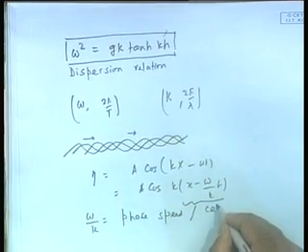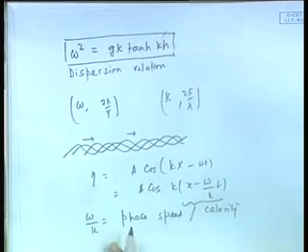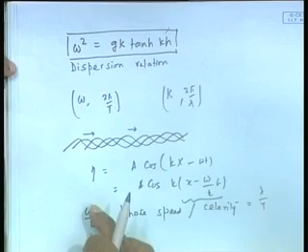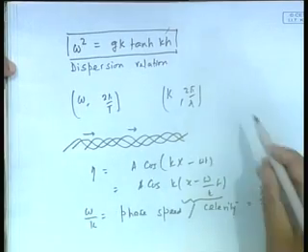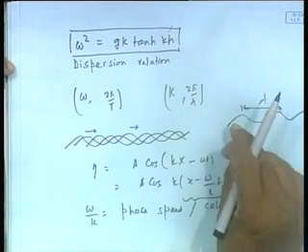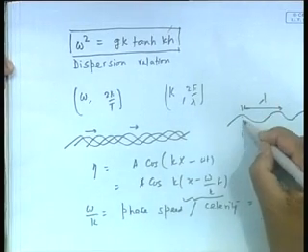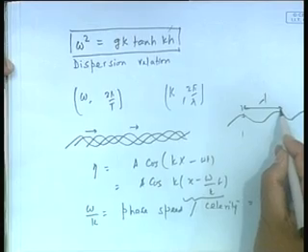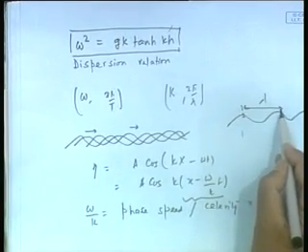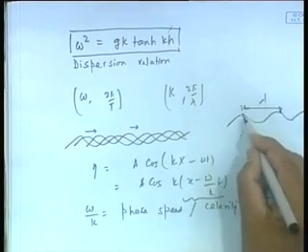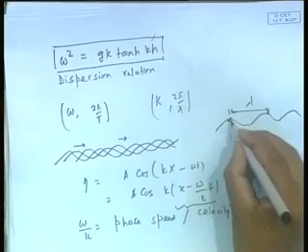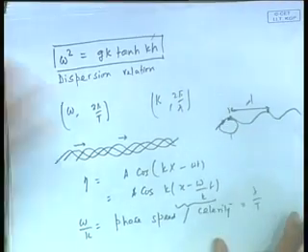or some people call it celerity. And it is interesting because omega by k is nothing but lambda by t. If you see, because omega is 2 pi by t, k is 2 pi by lambda, and obviously it makes sense because what is happening is that this is lambda and the time for it to the form to actually go down one cycle and come up, which would imply as if this has gone here, is t. So therefore you would think this form has travelled from here to here in time t. So this is what is phase speed. Remember, it is the form that is travelling, not the particle itself. We will see later on that the particle here, they move in a circular fashion. We will come to that in a minute.